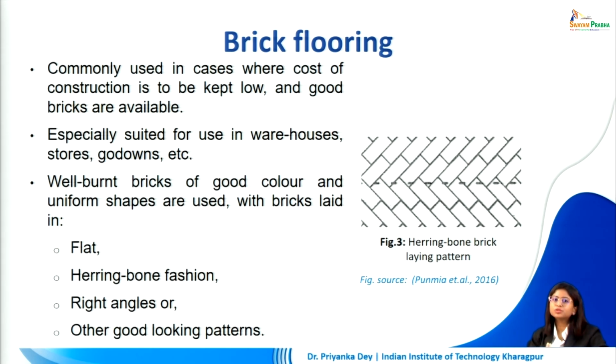Now, well burnt bricks of good color and uniform shapes are used, and the bricks are laid in different patterns. We could either put it flat, we can have a herringbone pattern to it, right angles, or even other good looking patterns. Now, when we were studying masonry, we had seen various types of patterns which we can use in arranging our bricks. So, the ones which are applicable at the flooring level were towards the fag end of the lecture. So, that should give you an idea about the different patterns that we can use for brick flooring.